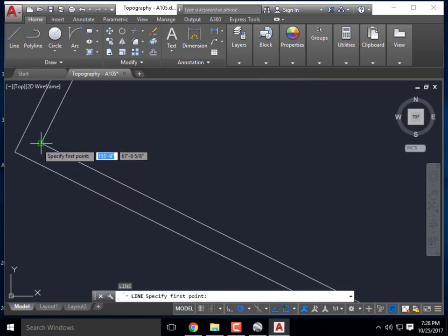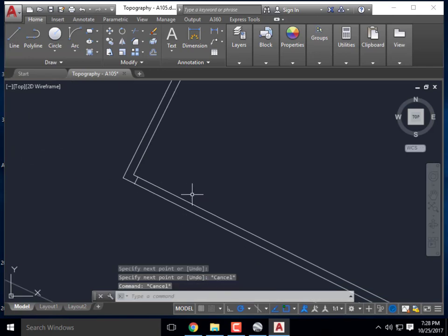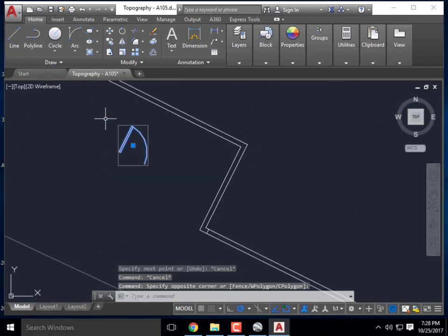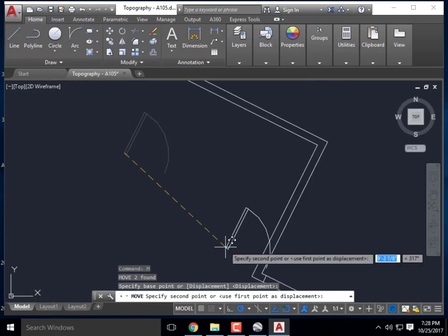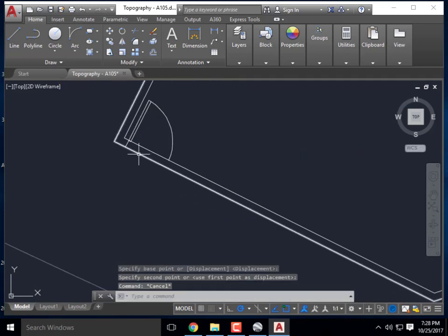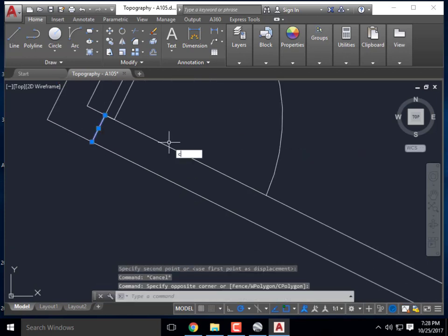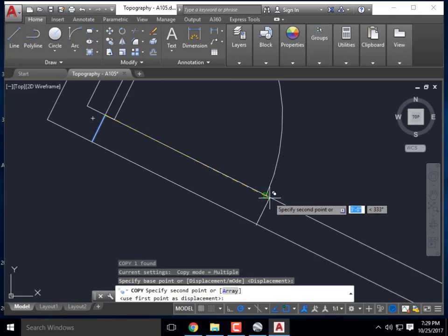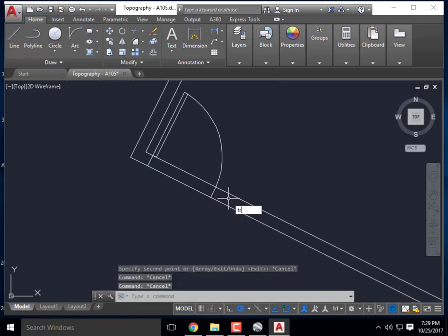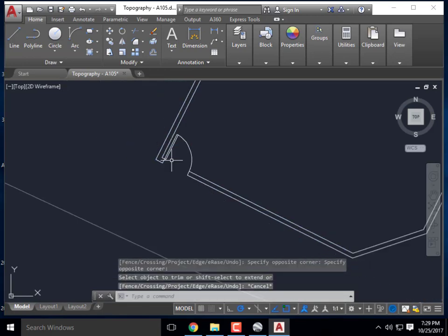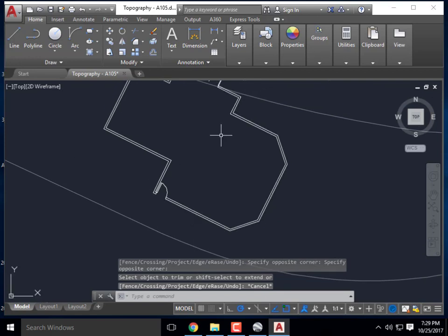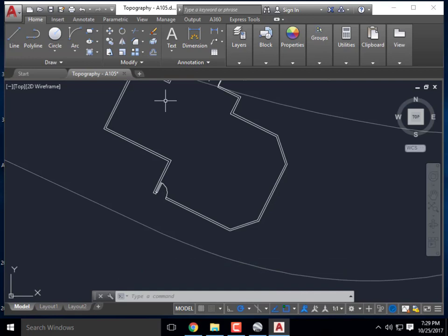I'm going to make a door jamb, 4 inches. And now I can snap this to that jamb, copy this over, like so, use my trim tool, and start to place all of my doors in a much more fluid and easier fashion. So that's the group tool.